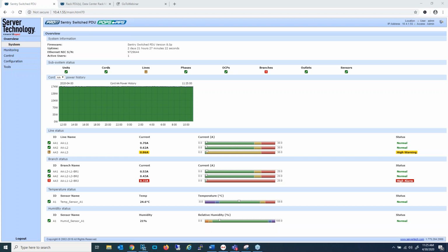Sure. Yeah, right. I did not use that type of PDU for my demo. I've logged into a North American PDU modeled in what's called a delta fashion, where all of the outlets are wired with two hot lines. What you're seeing is a PDU that is a 3-phase Y, a WYE.